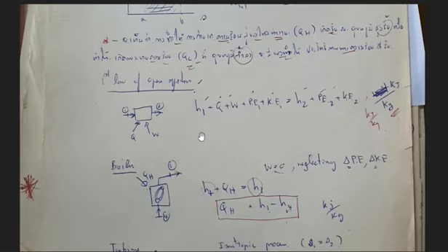So we will have the enthalpy at state 1 coming in, right? And then we will have heat coming in and work coming in. If it is heat going out, the sign would be minus. If we have work going out, again the sign would be minus. But in general, we will write it as a plus.